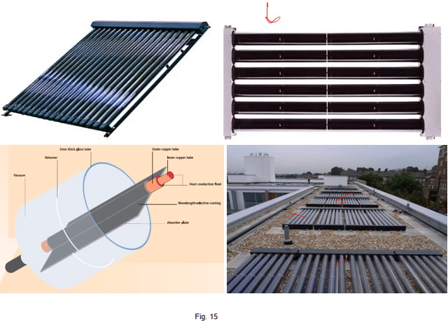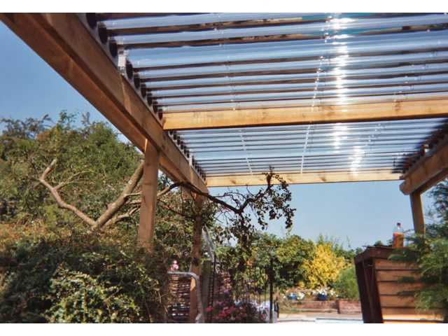Let me take one of them. This is a cylinder made from glass. Inside there is a sheet, as you can see here, and we call them fins. These fins are connected to a metal pipe, and there is a small pipe inside this pipe. The current flows inside the internal pipe and returns back through the external pipe, where it gets heated. Fins help to capture more energy.